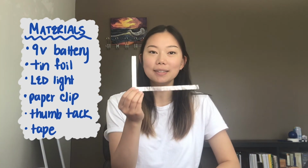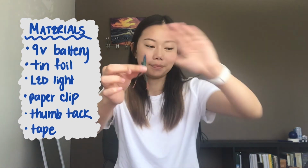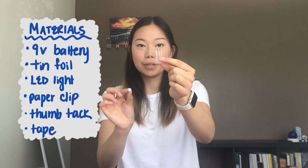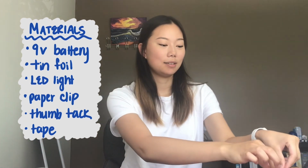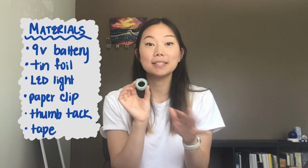For our first experiment, we're going to make our own circuits. So what you're going to need is a 9-volt battery, some strips of tinfoil, a little LED light, or what I have here is just a Christmas light that I cut off. And then this is optional, but you can get a paper clip and a little thumbtack. Plus, I'm going to be using some tape just to make sure our tinfoil doesn't move around.